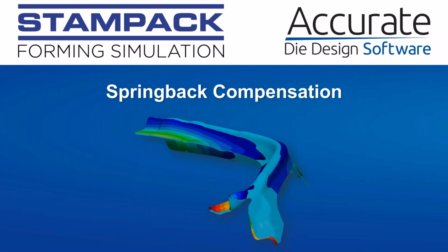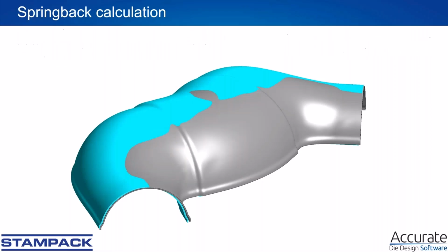Let's speak once more about springback compensation. I have another example for you. This is a typical part where springback is difficult. You see here the sheet after springback, and this is the sheet before springback. The part is maybe 600 millimeters long, I think, and in this area we have, I think, 3 millimeters deviation to the nominal.